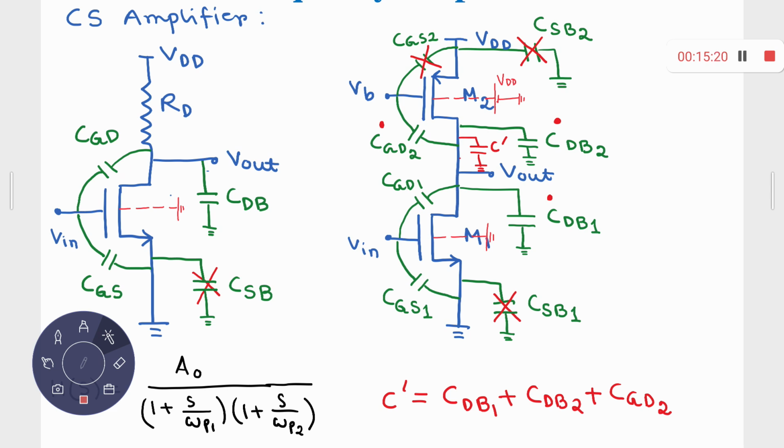So therefore, both of these two terminals, gate 2 and source 2, because whenever we consider the effect of the capacitors in the frequency domain, we will obviously perform the AC analysis, right? Because for DC, this capacitor will act as an open circuit. So you have to perform the DC analysis and the AC analysis, and for AC, both the gate terminal for MOS2 and the source terminal for MOS2 are connected to AC ground.